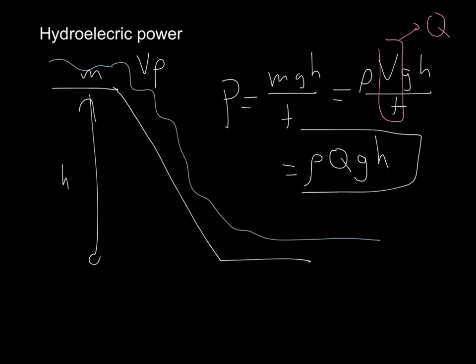What some people do is pump water up during the day so that they can use hydroelectric power during the night. So for example, imagine that I have a coal station and I wish to store some of the power, because, for example, people are not using enough electricity, so I have some spare power. Well, I use that to pump water up a certain slope, and then at night when people do need electricity, I can use this water to generate electricity. This is called a pumped storage system.